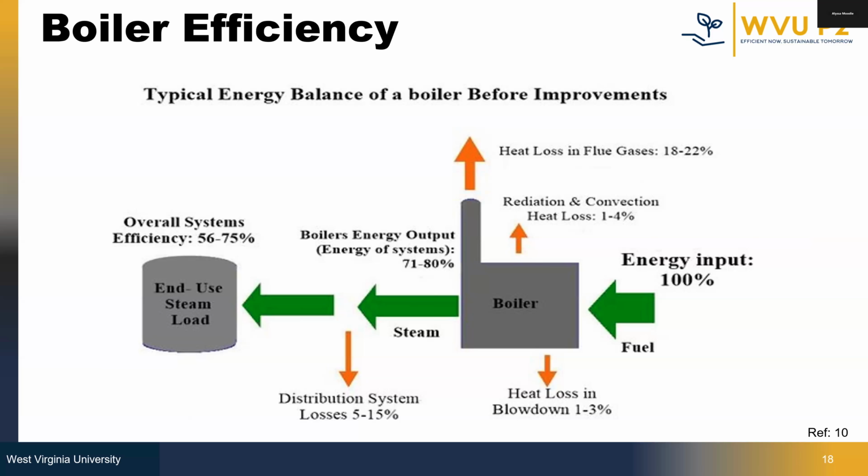And the final source of loss will be due to blowdown, which is up to 3%. So water blowdown releases hot water to manage impurities, and that results in this minor heat loss of about 1 to 3%.